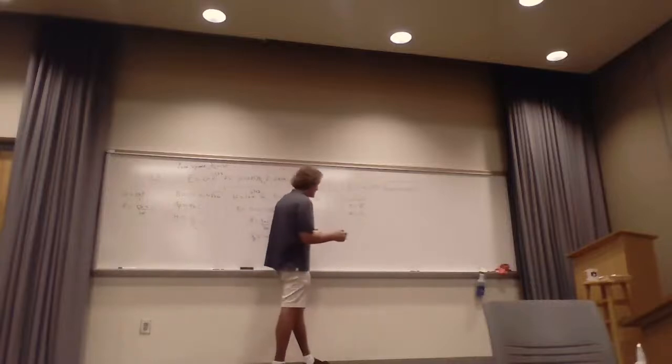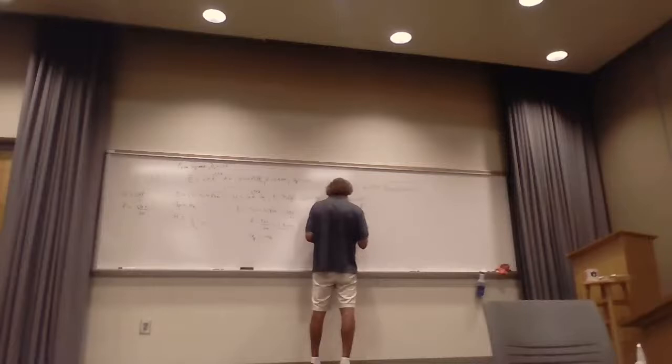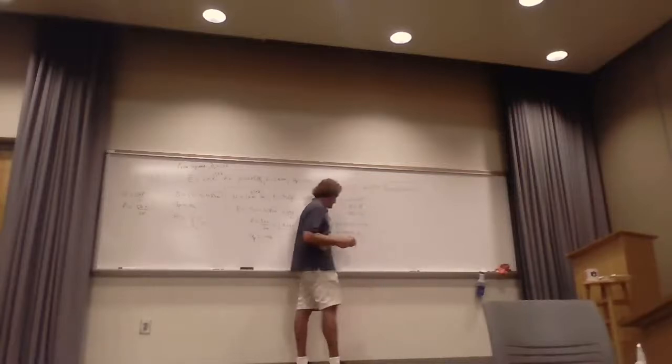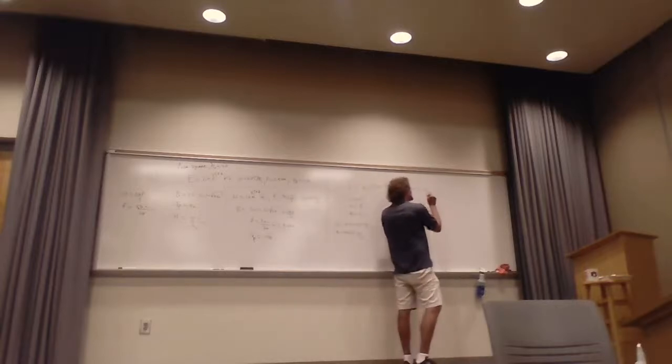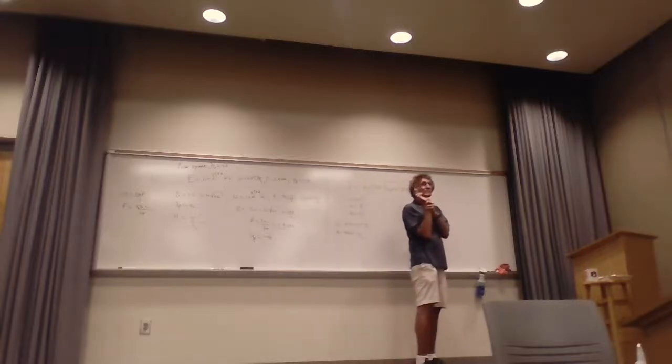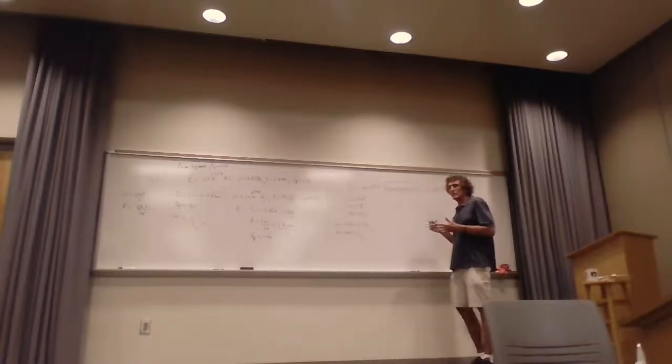Epsilon naught, of course, you have to know. You can use 8.854 times 10 to the minus 12 farads per meter. And mu naught, 4 pi times 10 to the minus 7 henries per meter. But it's turning the crank. And when you do this on this one, I asked for this in rectangular. Can you give me the values? Yes, sir. 68.3 plus j 86.6. Y'all remember doing this, by the way?